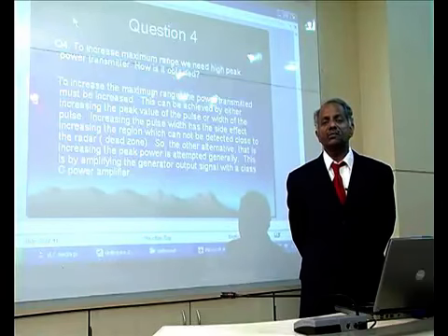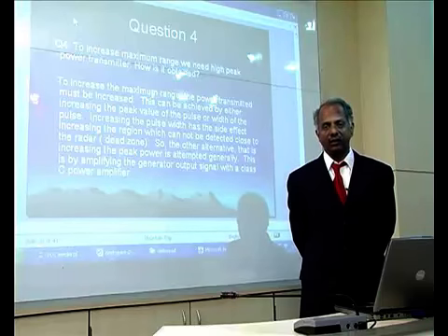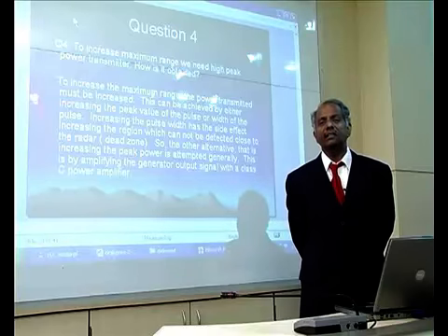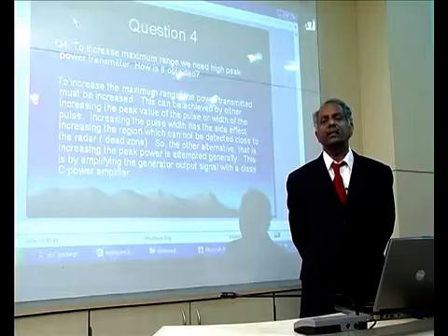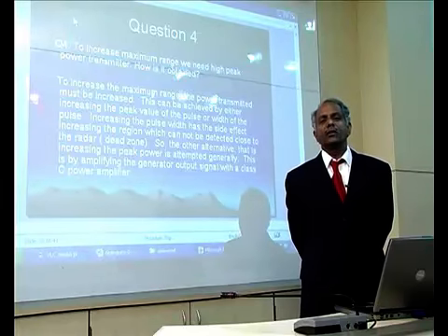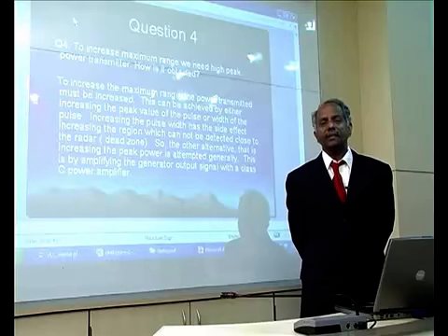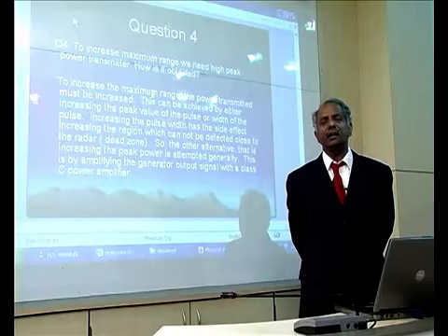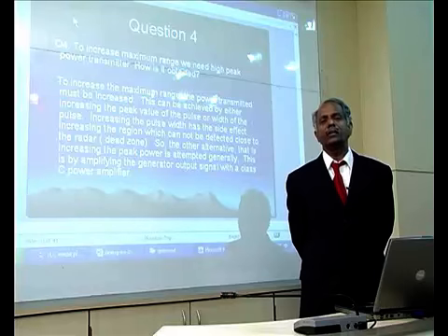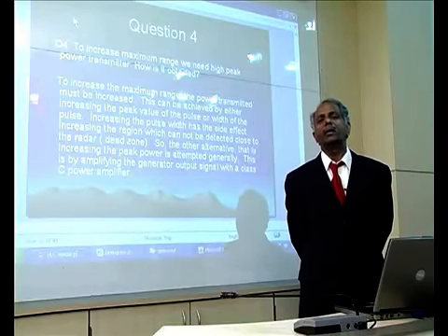See, power amplifiers will give rise to good efficiency of the order of 90% or so, but with a penalty on the distortion of the signal. But as the signal is going to be distorted in the atmosphere anyway, we allow a certain amount of distortion in the signal at the advantage of getting higher efficiency. Hence, we use class C or even class D amplifiers towards the end of the transmitter chain so that we will be able to transmit high peak power.